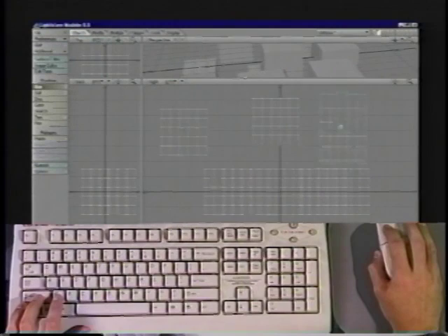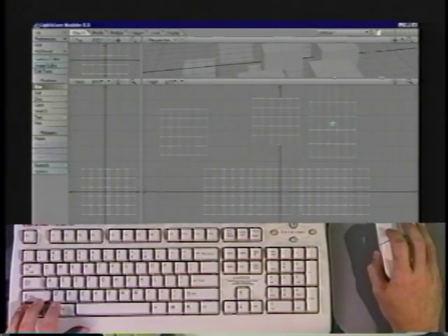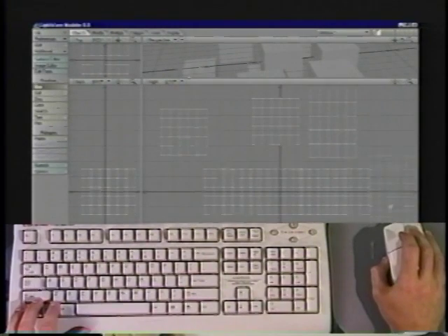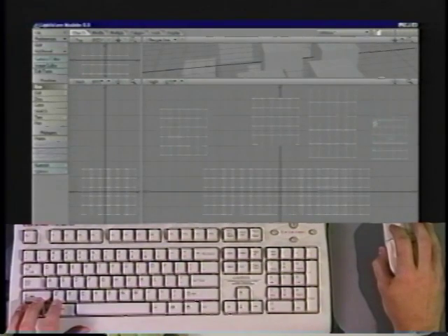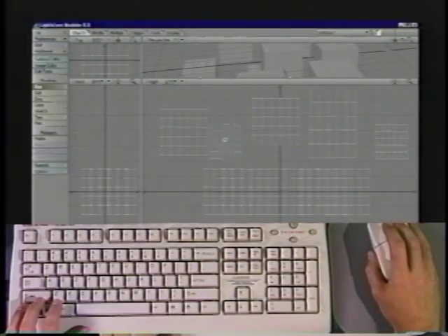So that could be useful if you're making a city and you want to make all kinds of different sizes of buildings. You could very quickly go in and resize a few of those buildings. Hold down the left mouse button on the center cursor and I can move those boxes around. And if I do it on the right mouse button, it creates the copy and I can drag that out as a new copy. So it's very cool. I can create these multiple copies and I can go in using the left mouse button to adjust them, and once I have them adjusted like I want them, I can go in with the right mouse button, hold it down, grab that, bring it out, and then left mouse button, adjust it some more.